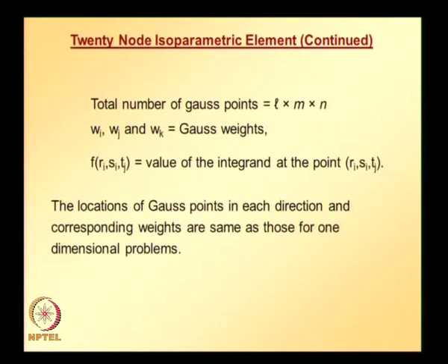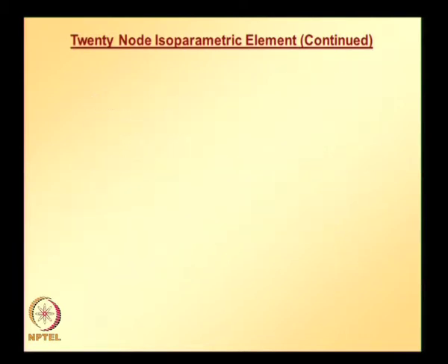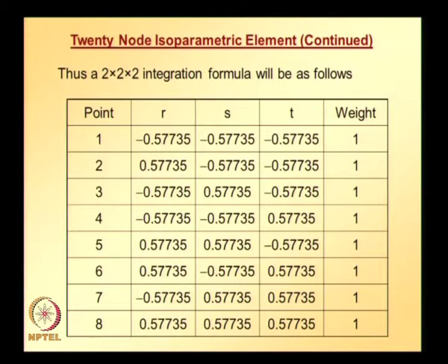This is just for completeness, I am showing you numerical integration in 3 dimensions again. And for 2 by 2 by 2 integration, the coordinates and weights of various integration points are given here. Adopting this kind of formula, we can evaluate each component of the element stiffness matrix.